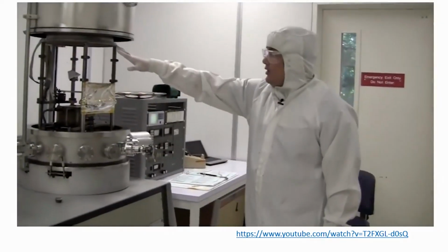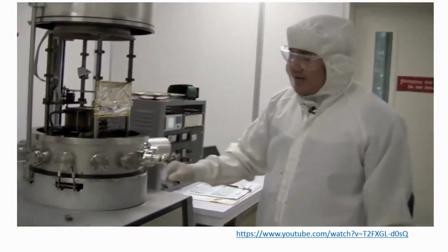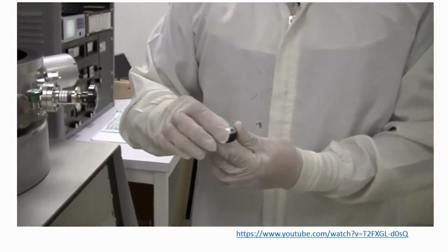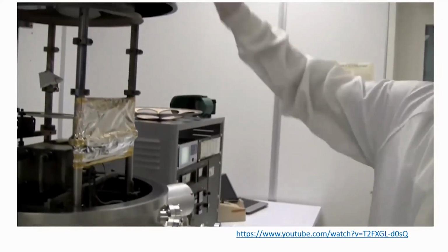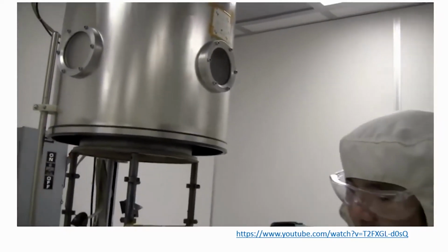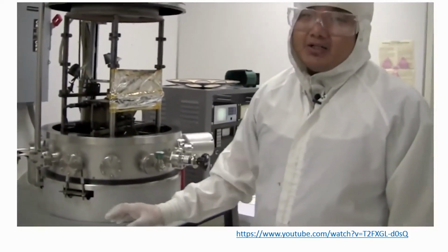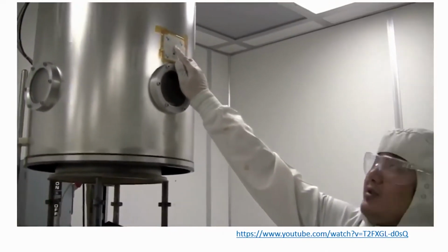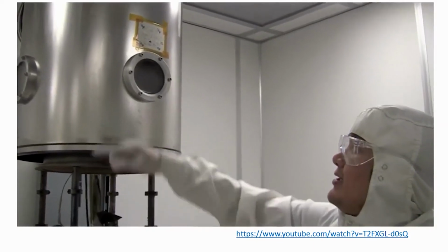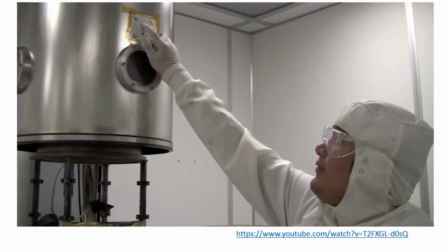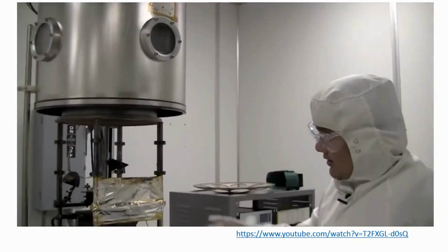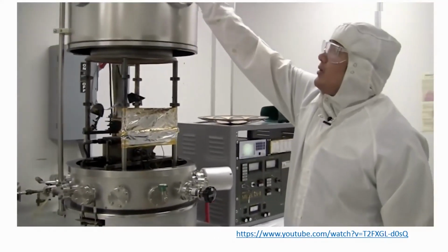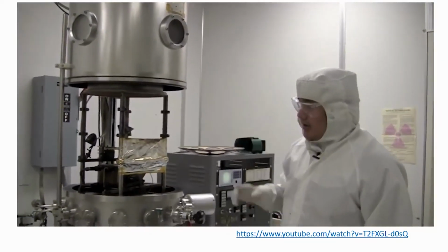Once we have our sample and substrate loaded up here, we want to actually load in our crucible that contains the metal that we want to evaporate. This system actually has 4 pockets that you can put this in. To put it in the right pocket, we would need to first use gold as a reference. And since we're doing titanium, we want to be 1 before gold. So we look for gold, and then we rotate the system with this knob here. And we can see the open crucible for titanium, and that's where we put it in. So we'll do that now.